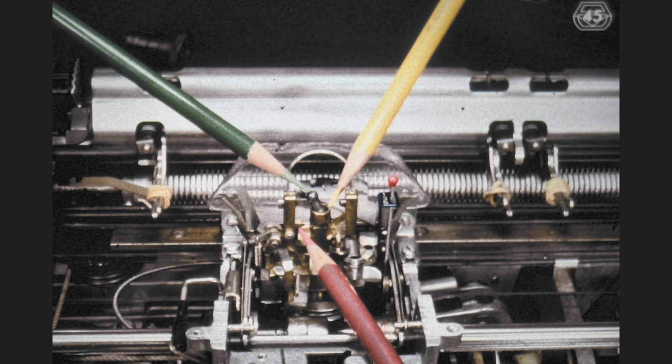With the upper ball socket, the dog bone, and the lower ball socket, we have basically a universal joint which allows us to rotate the upper ball socket, or the type element, at the same time that we tilt the tilt ring into any position. We can use any of the 4 tilt positions we need in order to print the chosen character. The blue indicator in this photograph shows the portion of the tilt detent which controls the rotate detent. The rotate detent is mounted under the tilt ring, and it came out with the ring when we removed it.